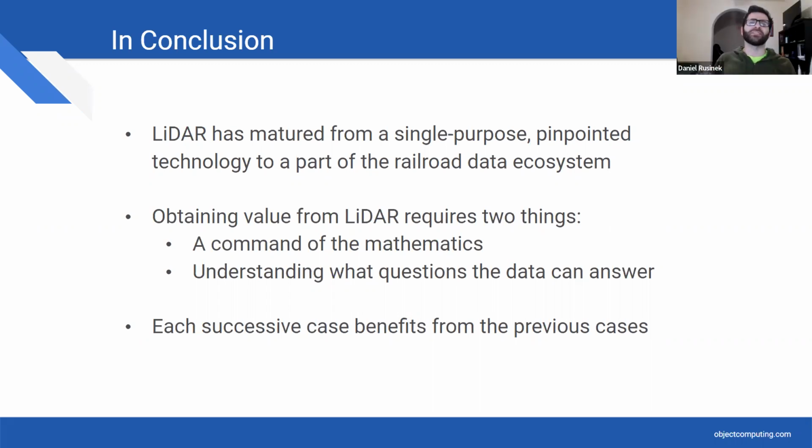And one kind of interesting side note: we have to run the LIDAR. We can't be stopping and keeping trains from operating while we're surveying. Oftentimes we run into situations where there's maybe a stopped train on the other track, which creates some shadow zones and starts blocking some of the data. That may or may not be something that the companies care about, but we do keep track of that, and we're looking into ways to identify those as an obstruction. We can at least let our clients know that there's an obstruction here, and then they can decide what kind of action they want to take.